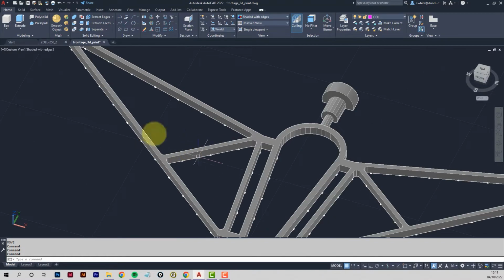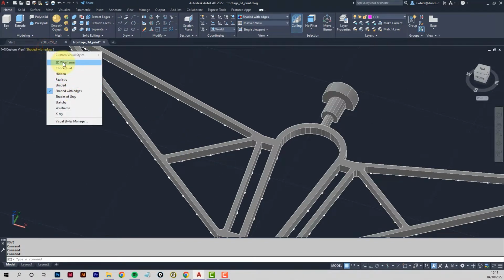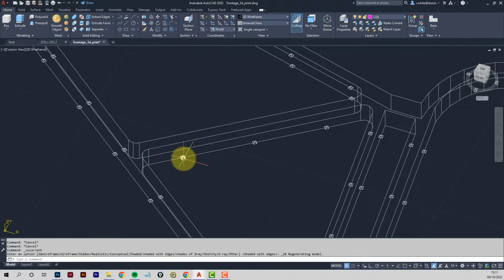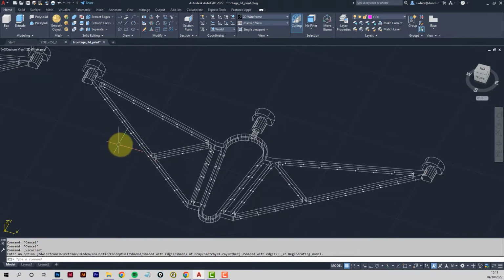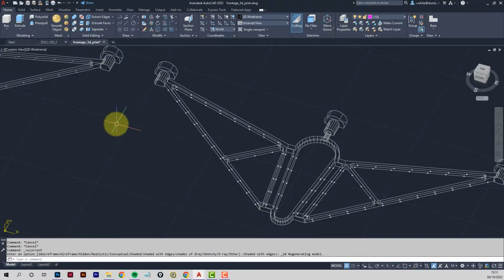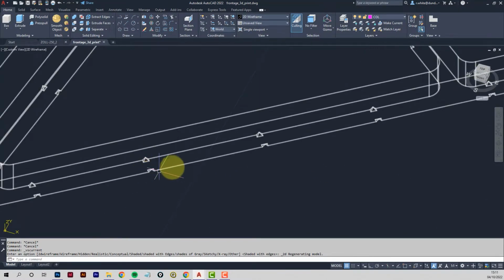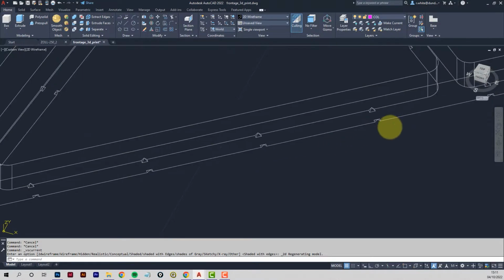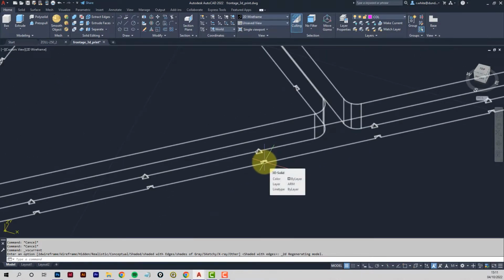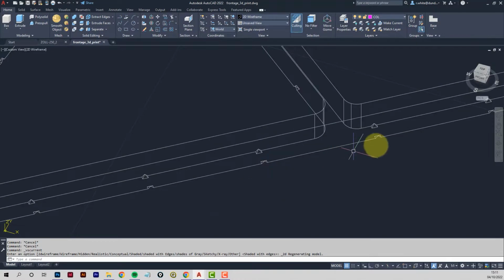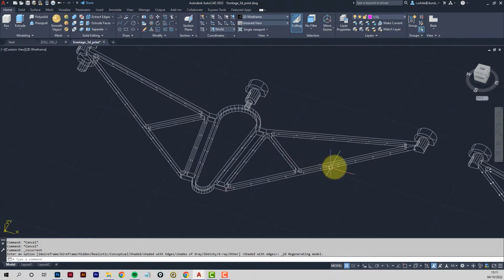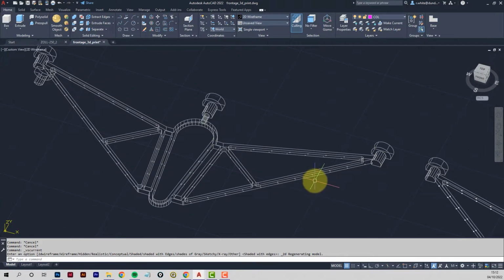You can see here on this bit of model, if I put it to 2D wireframe, these little pyramids, I use these extensively on my models to help get a better stick down to the printing bed. So you subtract these little pyramids, and it creates little pause points for the printer nozzle, like a tack weld or tacking when you're making a piece of clothing. You put in the pins first, and then you come along and do the sewing. So very similar principle, and they're so small that they don't often show up on the model.